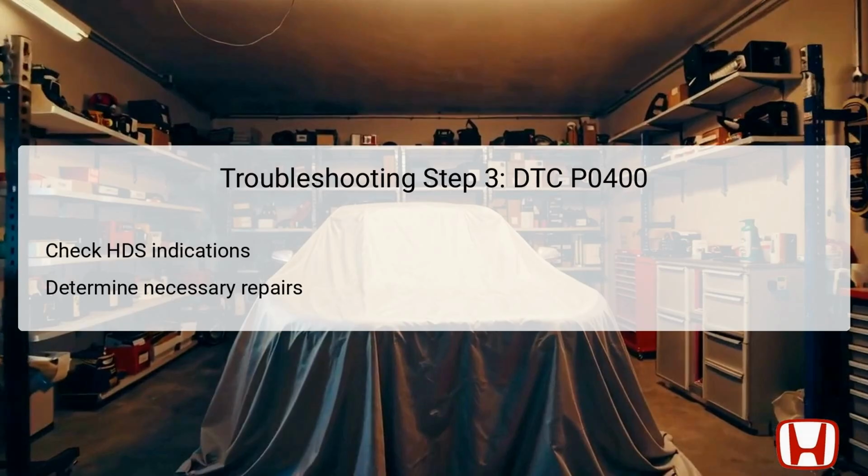If the HDS indicates a failed status, it suggests that the issue replicates, confirming a fault within the EGR system, likely indicating a need to replace the EGR valve. If the status shows as past or intermittent failure, that means the system is potentially functioning correctly at that time and calls for further investigation.